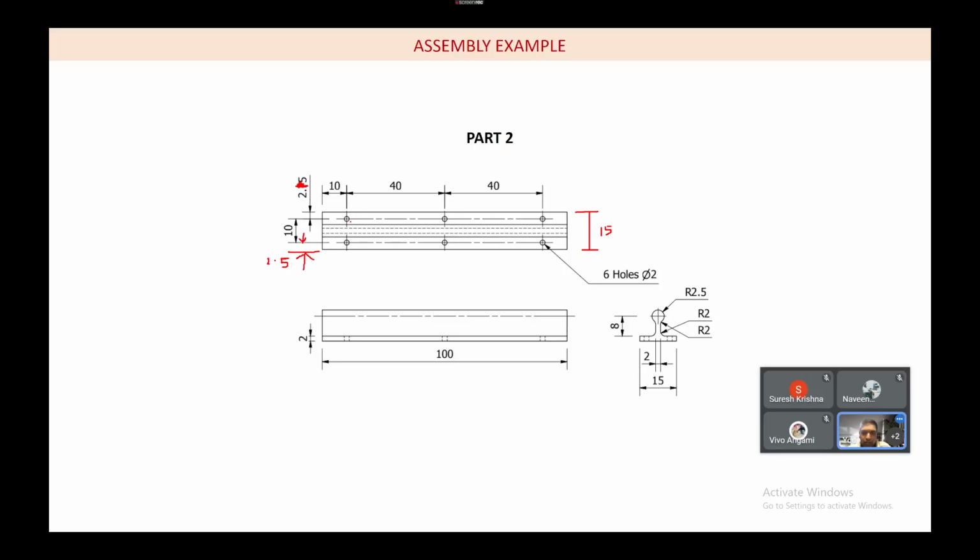Okay. So now again go to the home, create the new part, next part. So we have first this sleeve we will create, and then we have to create the slider. So now let's create the sleeve. The sleeve, if you see, is located in the left side view only. So front view, and this is the left side view.